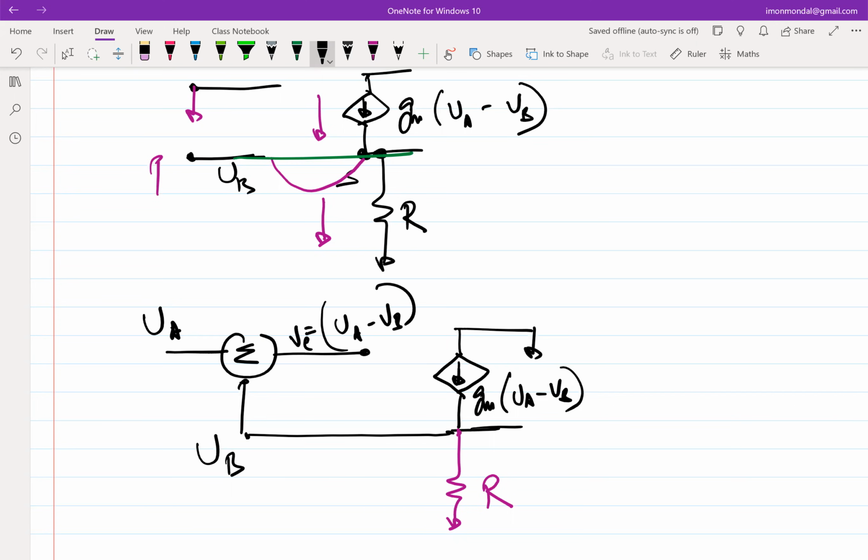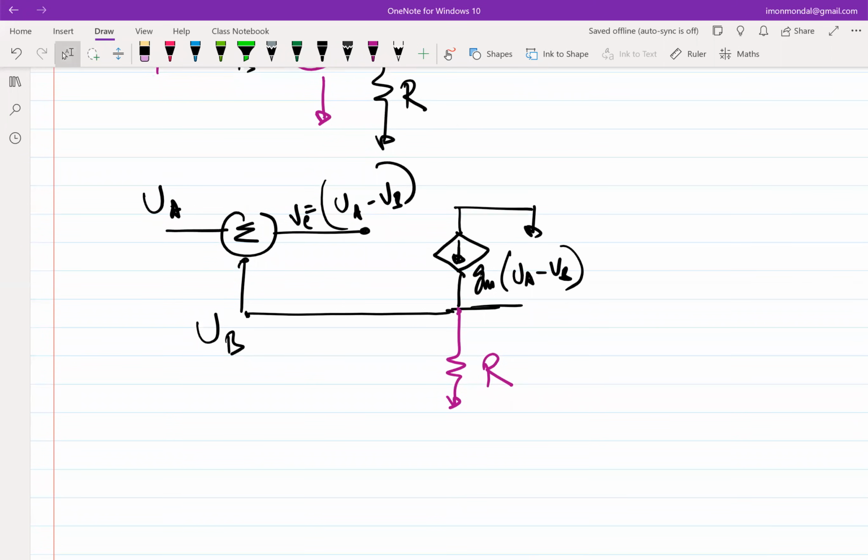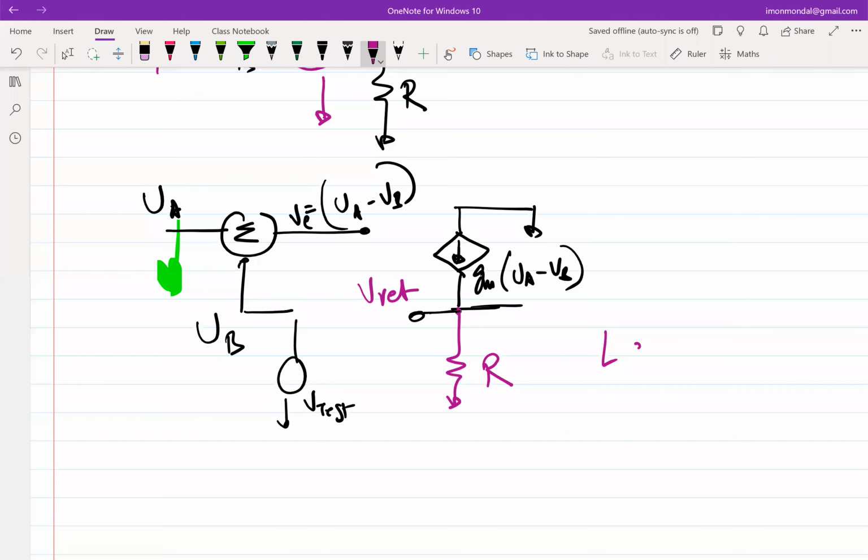So this is a negative feedback way of describing what your transistor is, the stuff in the black. If you have to figure out the loop gain of this negative feedback loop, what will you do? First ground VA, then break the loop anywhere, let's say here, apply a test voltage, and figure out what the return voltage is. What will be that loop gain? Can somebody calculate?